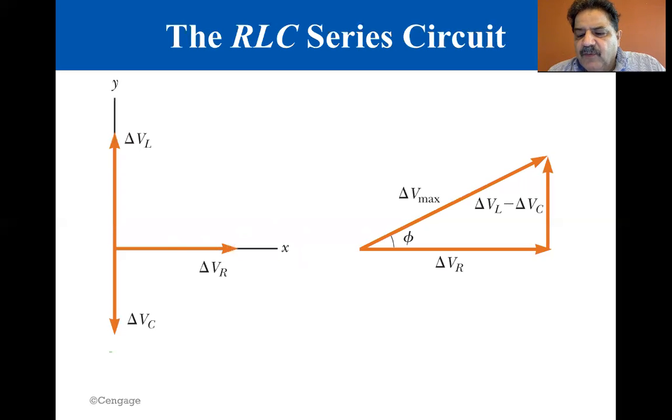Phasor diagrams are useful for analyzing the series RLC circuit. Voltages in phase with the current are represented by vectors along the positive x-axis, and voltages out of phase with the current are phasors in other directions.